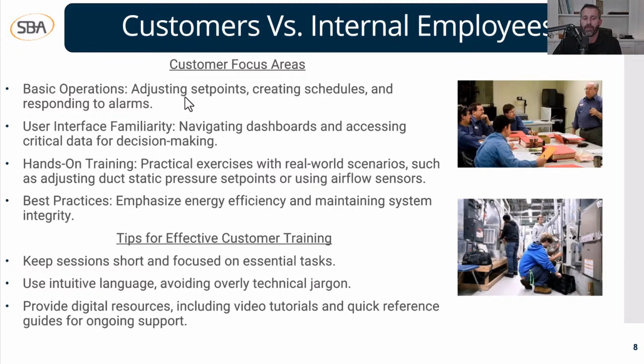We need to include adjusting set points, teaching them how to do that, how to create schedules, and also how to respond to alarms. We might even throw in teaching them how to create a trend or a data log, things like that. Also train them how to use their user interface: navigating all the dashboards, the floor plans, how to get everywhere, where everything is located, and accessing critical data for decision making. Teach them how to make a trend, things like that.